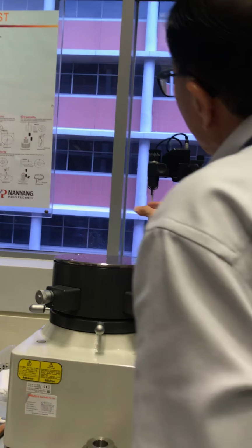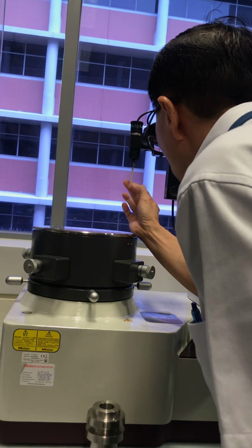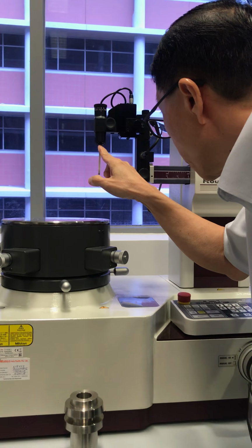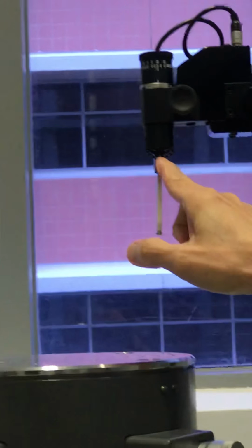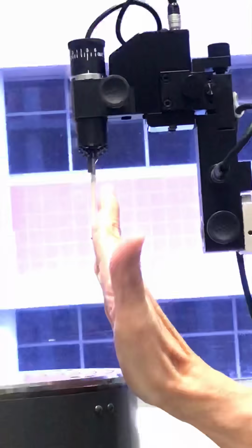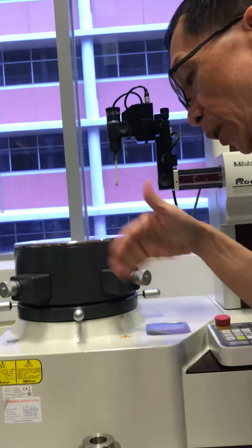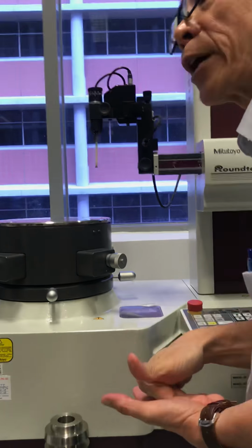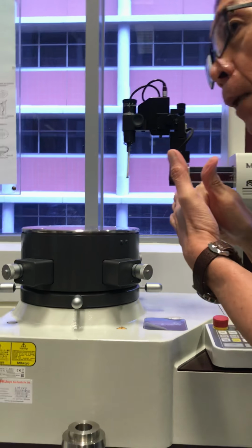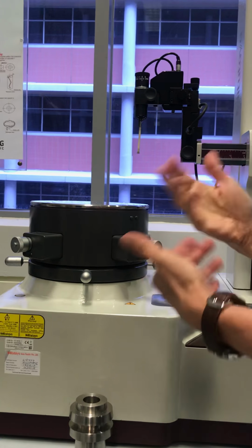And this probe, make sure it is at 0 degree. There's an angular movement here. The reference point is the white dot, and the 0 in line. If it's in line, you will find that this sensor is a bit inclined this way, so that when you touch the surface, there will be no shaking. When you touch to the actual force, the sensor will be vertical, so there's no cosine error.